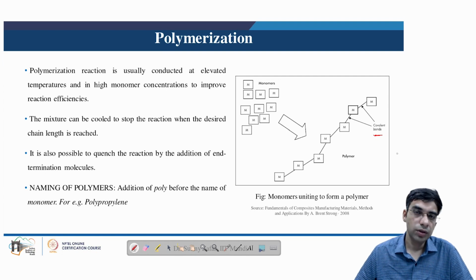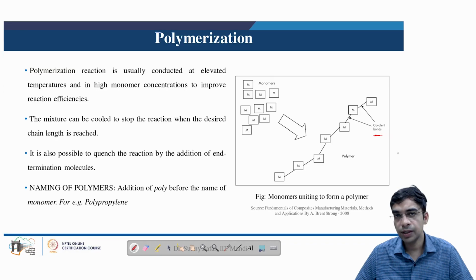And because of this long structure, they mostly follow an amorphous configuration while the polymer solidifies. So unlike metals, the randomly oriented structure of the solidified polymer chains gives unique values as well as characteristics to these materials.